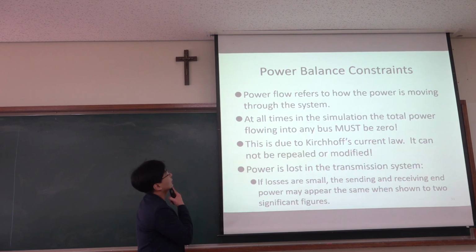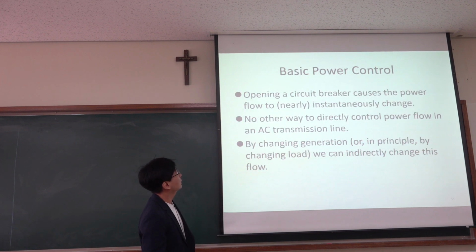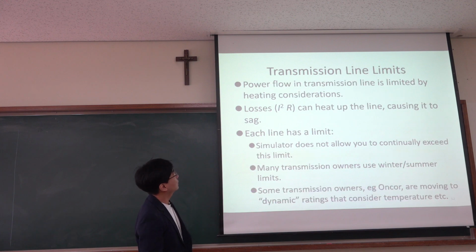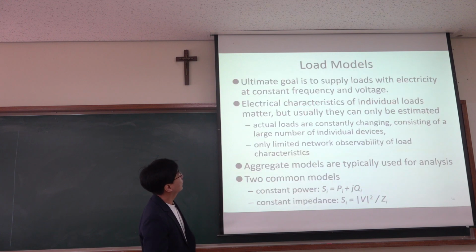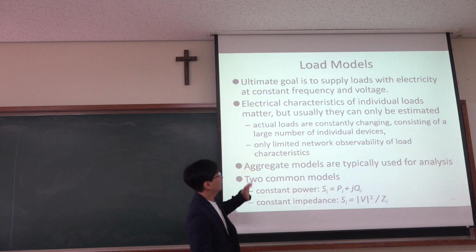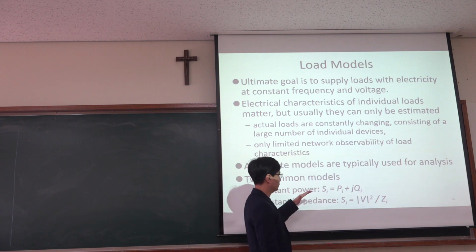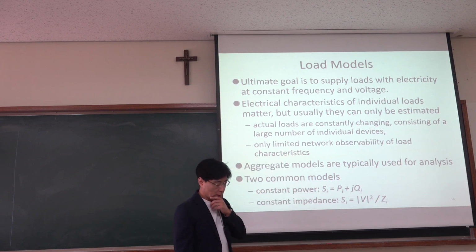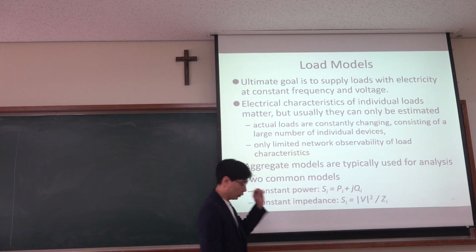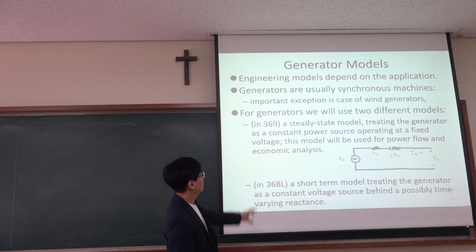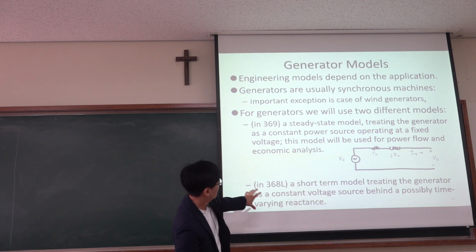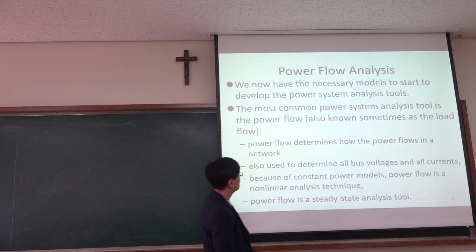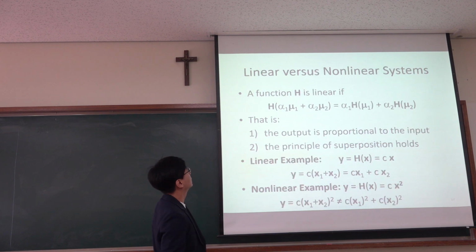And then we have some power balance constraints, power control, transmission line limits, overloaded transmission line. We have a load model, which assumes the constant real power and reactive power at the load bus. And we have a generator model. And then now we can do power flow analysis.